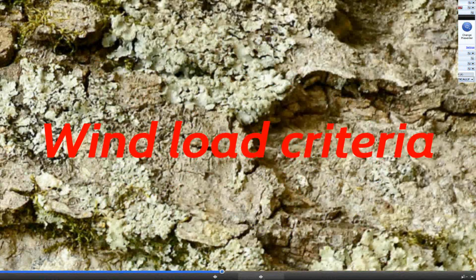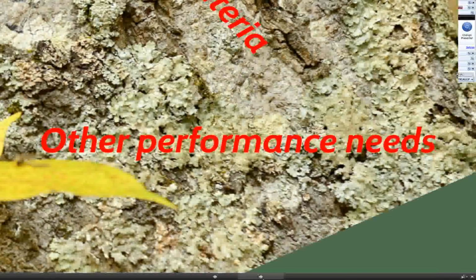And Lewis, I'd point out, on the wind loads, a common mistake would be, as you're showing on the table, particular fasteners and things like that. It might be they use the product, but they don't use the fastener that's prescribed within the report. Exactly, and we're going to get to that very point in just a minute, Barry.